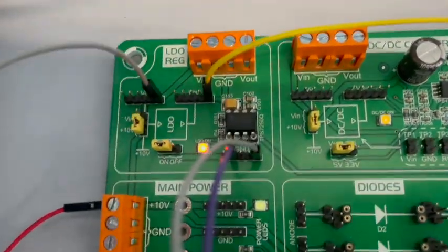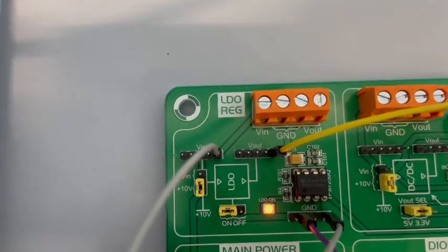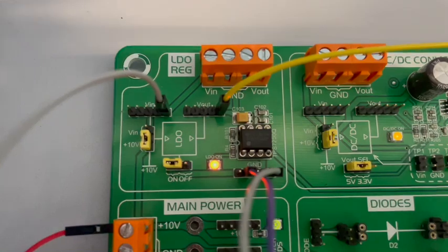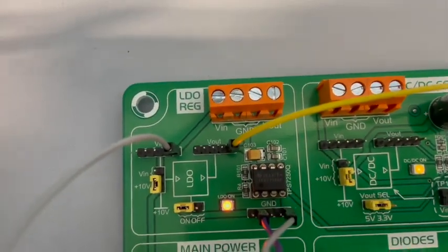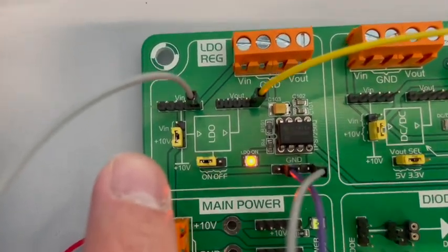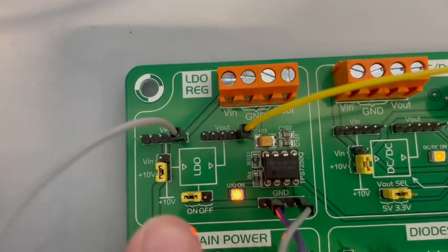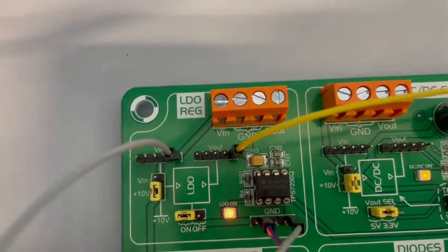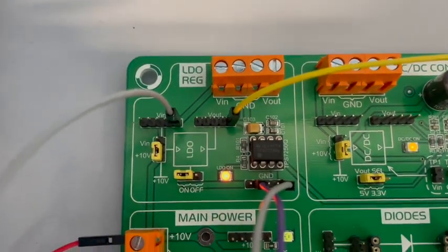So you have to connect. Here we have V in and V out. V in comes from the signal generator. V out goes directly to the oscilloscope. Here the ground connection, you connect to the ground. Make sure that it's on, and make sure it's 10. The jumper is connected to plus 10 volts, and here the jumper is connected to on. And it should be on once you turn on everything. It's a simple circuit, you just need to connect V in, V out, and the ground connections.